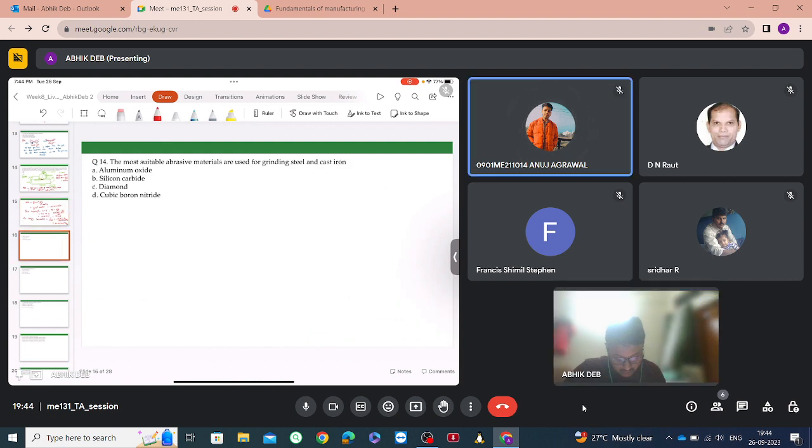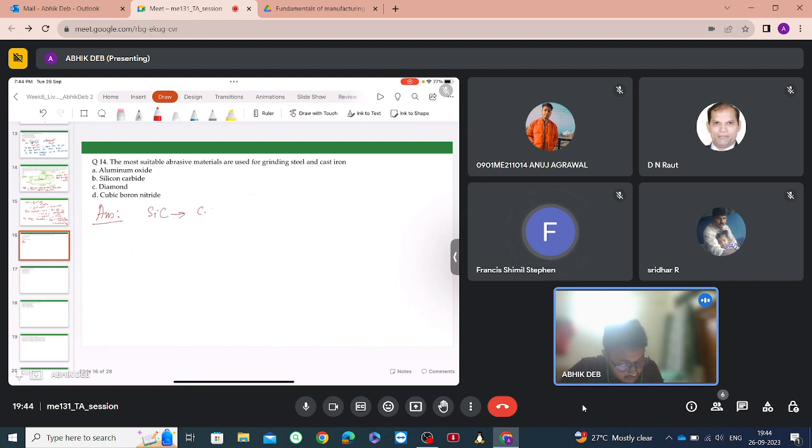Yes, sir. So coming to the next problem: the most suitable abrasive material for grinding steel and cast iron is which of these? Silicon carbide. Silicon carbide is basically used for cast iron, for brittle materials, and some other steels which are